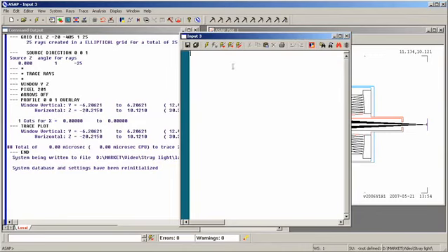So we'll begin here. The very first command I'm going to enter is system from cas. Recall that cas was the name of my binary file. It's the file that contains my system geometry and the optical properties. By saying system from cas, I'm reading that geometry into ASAP's memory so that I can work with it.